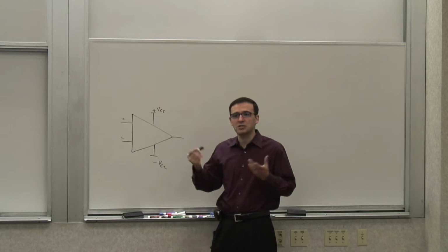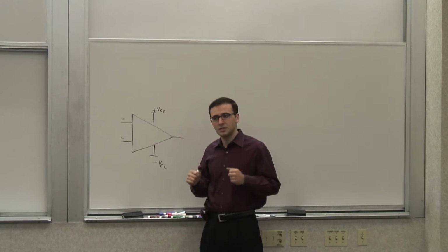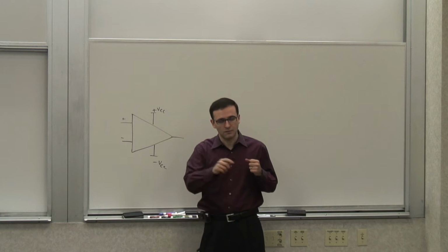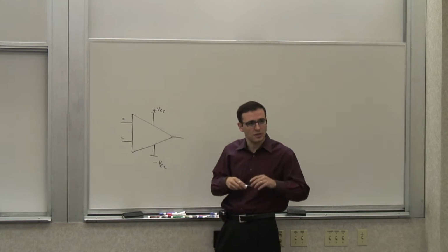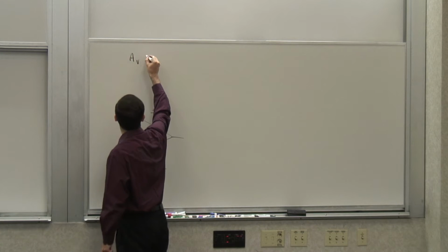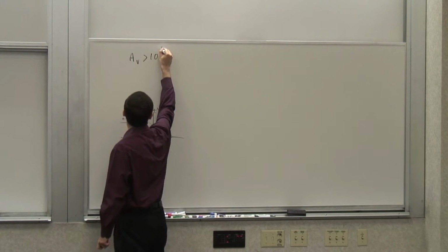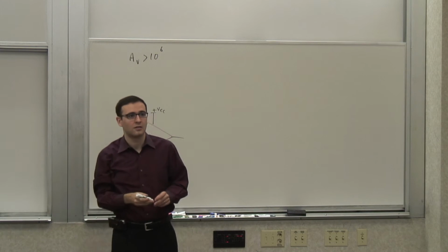So that's the kind of op-amp I want to make. And then let's say how much gain I want. Well, let's say I'm kind of thinking about having a reasonably large gain that I can use in feedback loop to control everything and reduce the DC offset error. So let's say a gain of, make it round, about 1 million or greater, the voltage gain of 1 million.